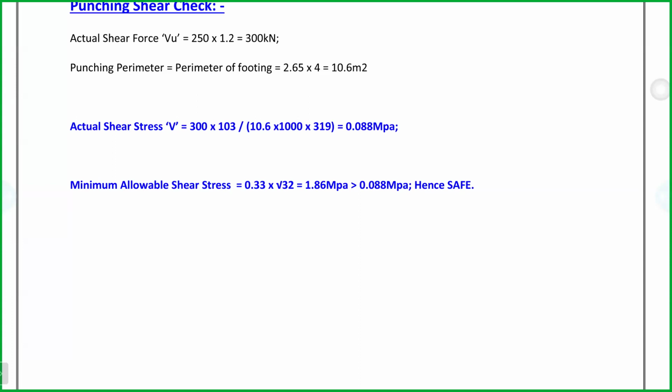You may have smaller, but let us go with this, because there should always be a backup. If you want to use 40, at least the spacing between the rebar is 60. Then only can I put the vibrator in and take it out. If you provide 40, first of all, you cannot insert the vibrator. Now the code is not matching. So these are all practicality and constructability matters you have to adopt. Code is the guideline.